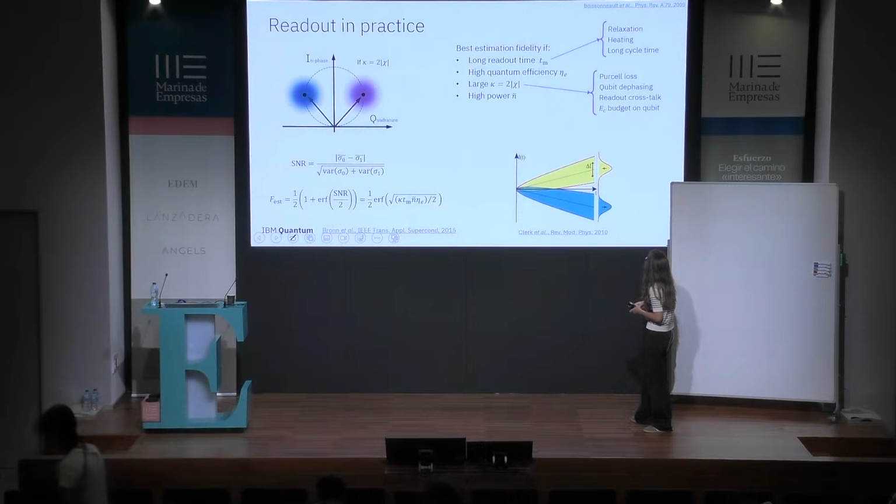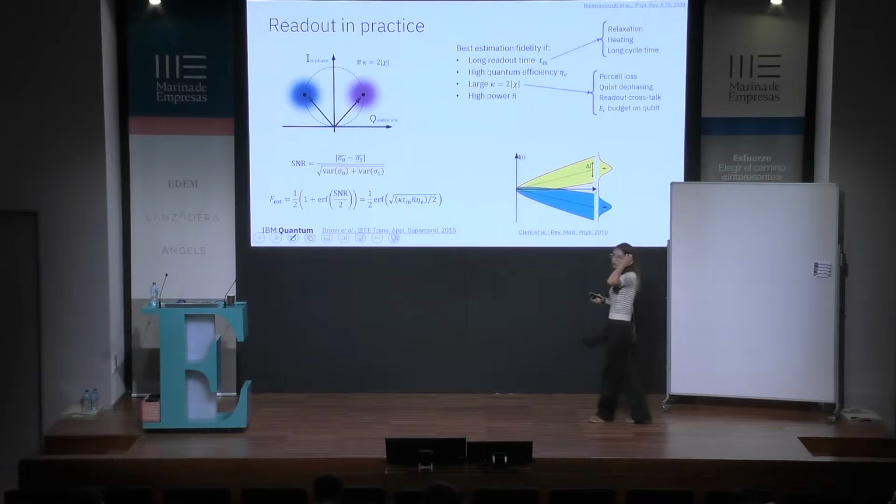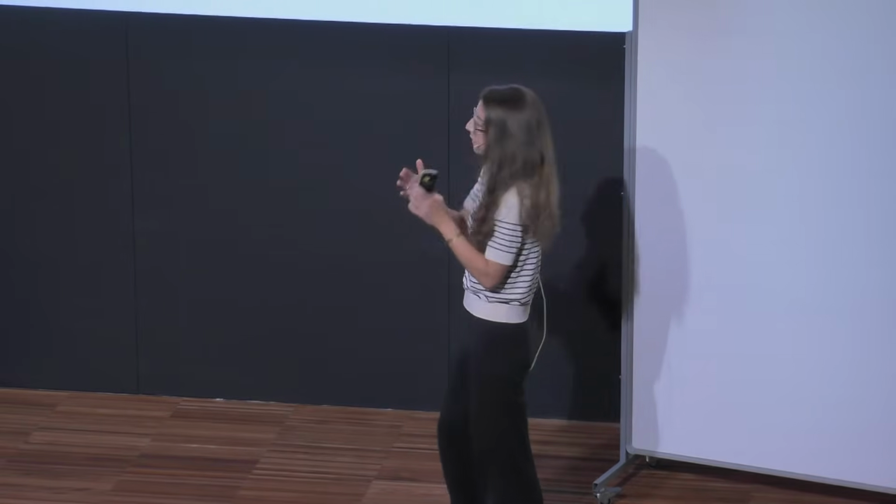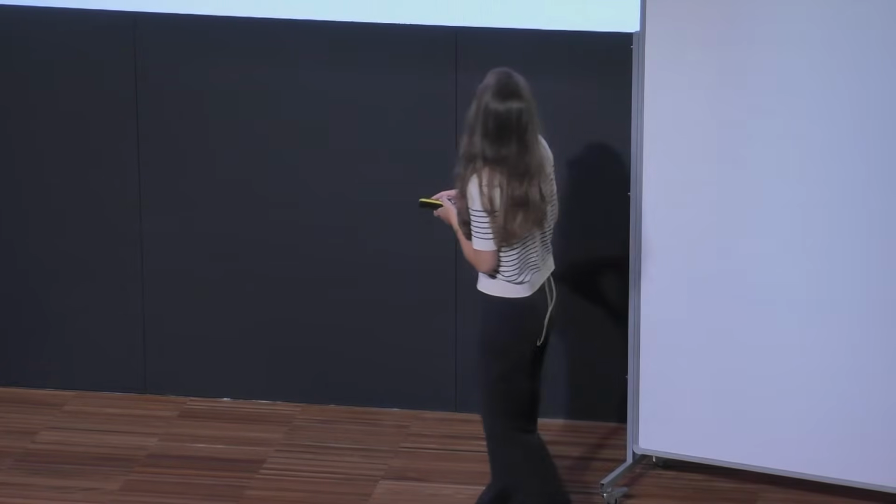We can also have readout crosstalk. So imagine you are working on these things at scale. You might have some band reserved for your qubit frequencies or whatever other frequencies you want to deal with, and maybe that restrains a bit what band you have available to place all of your resonators if you are multiplexing them in the same line. So if you increase kappa, the line width of each resonator, they can start actually overlapping a tiny bit with each other, so they can end up cross-talking with each other. And that would be a problem.